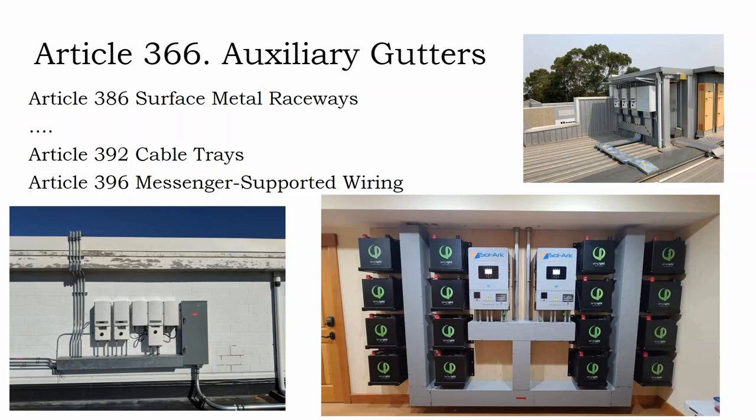Now, on top of that, getting all of this straight, making all the bends perfect, and all the kickoffs and setbacks, is difficult. When we initially installed this, where the array ends up here, we said, okay, we've got a 90-degree bend, and then another 90-degree bend, and a third 90-degree bend, and then our fourth 90-degree bend to land on here.